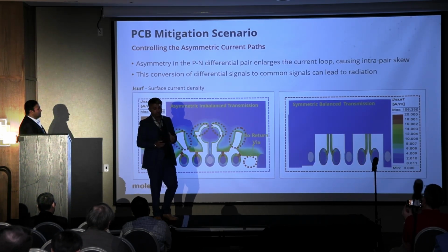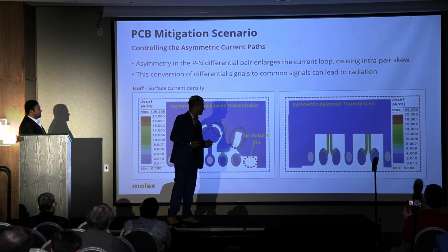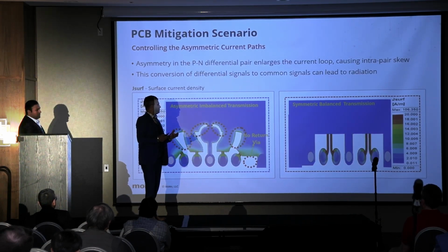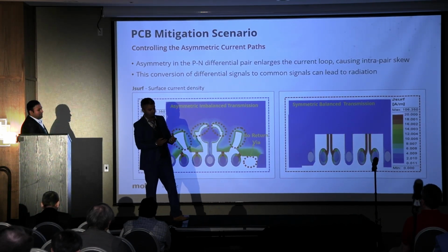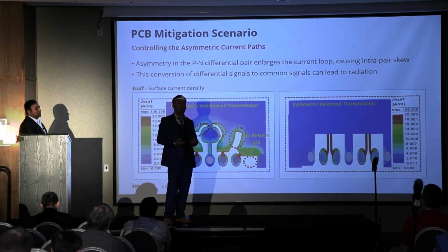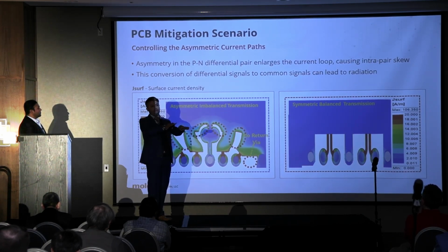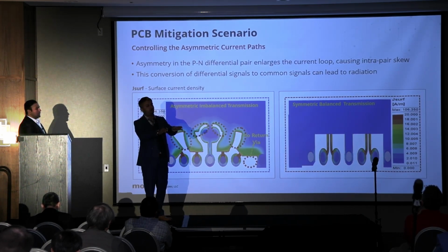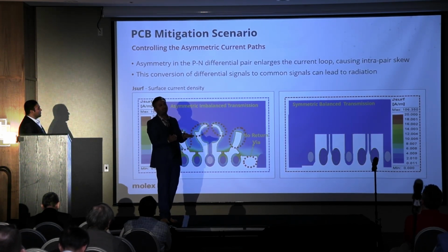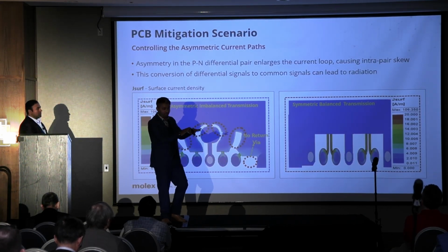So that's why it is very critical and important to control that mode conversion, right? And what are the ways to control that? In a practical circuit, as I told, the occurrence always happens. And the main reason why mode conversion happens is asymmetry. I'll have one line and another line, P and N, right? Whatever property this line has, be it length, magnitude, or phase, the other line has to see the same thing. It's like a Xerox. We have to make a perfect Xerox of the P line to the N line.